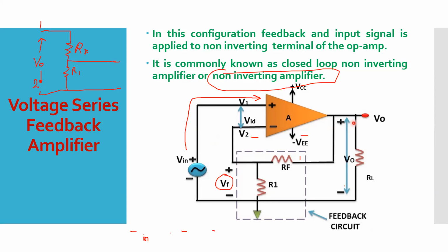But now you are using that op-amp with the feedback. So now you have to cross-check, or recalculate, what will now be its input impedance, what will now be its output impedance, and what will be its overall gain and bandwidth. So everything you now have to recalculate. Am I making this thing clear, everyone? Why am I asking you to recalculate the thing?